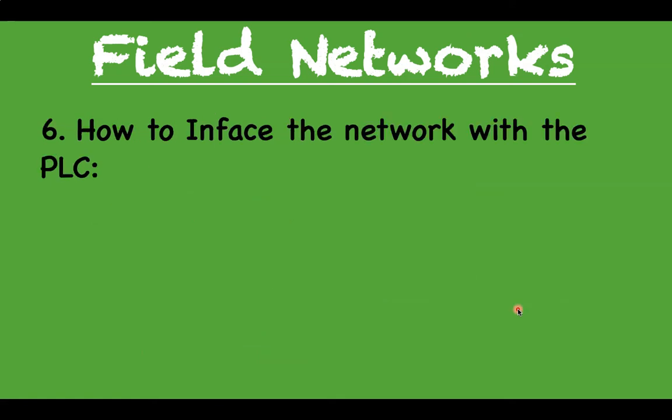Lastly, although not as important as the other points, but good to know, is how to interface field networks with the PLC. You need to know the software required. Some field network technologies come with a software package when you get them, so that you can configure the network and download the configuration to the master. Secondly, you can use the PLC programming software to set up the field network. In this case, you need to download the drivers, electronic data sheets, profiles, or plugins that you load to your PLC programming software and allows the PLC to be able to communicate and get data from the field network.